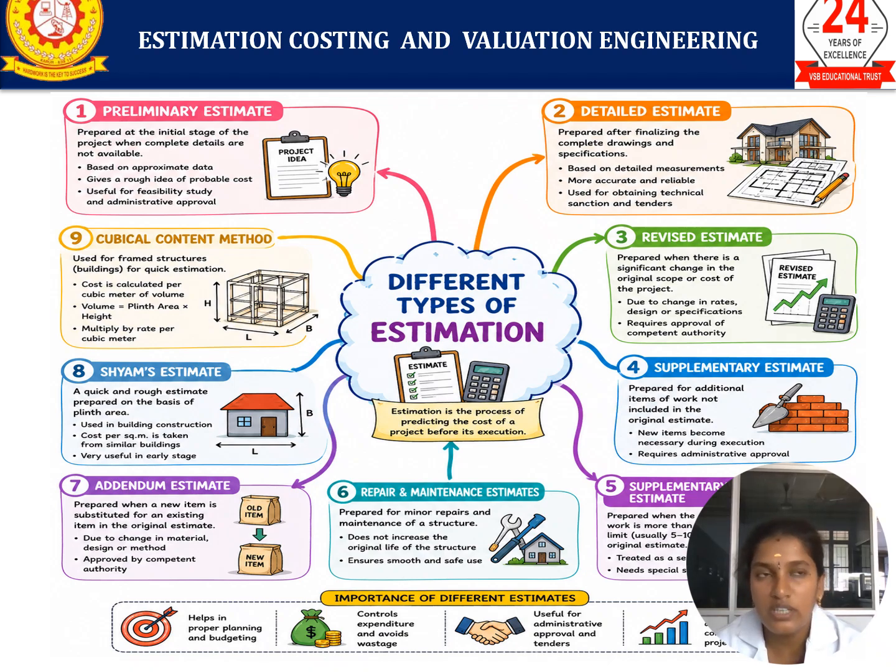If we are constructing a commercial building or a hospital building, and an emergency staircase is included at some level, likewise in the design or plan some additional items of work are included. That is incorporated into the supplementary estimate, because new items become necessary during execution. When we include this new item of work, the total estimate will change, so that will be a supplementary estimate.